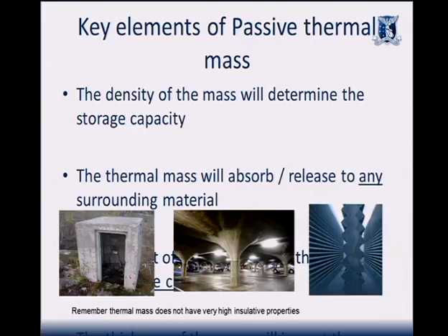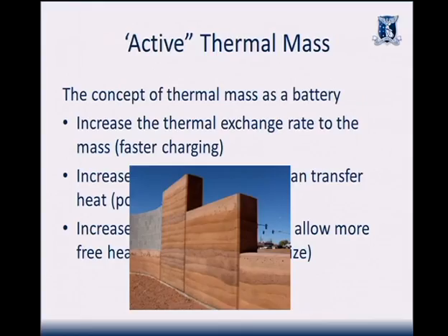So we can actually use this in our designs to not just have a block, well, a slab floor, but we can actually have a system that's made of concrete and blow air through it to cool it down or heat it up. So that's called active mass, where you actually exploit the properties of the thermal mass to be beneficial. Has anyone heard of the thermal labyrinth at Fed Square? Google it. It's really cool. You wouldn't have known it was there.